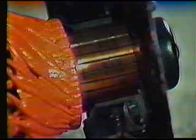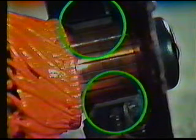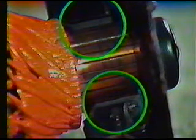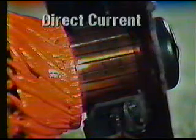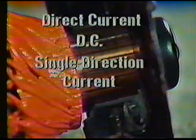At the rear of the generator are multiple brushes. These are conductive devices that contact the segments of the commutator. They are carefully positioned so as to only make contact with the commutator segments that are producing electrical current flowing in the desired direction. Hence the term direct current, DC, or single direction current.